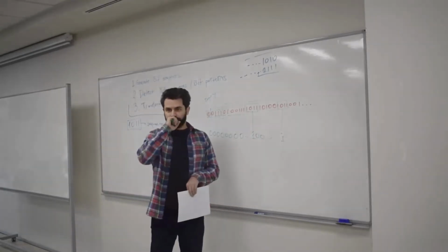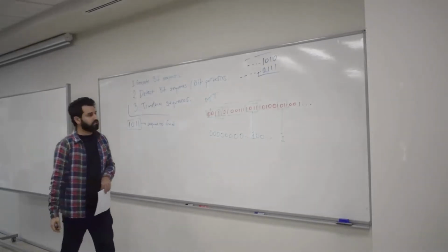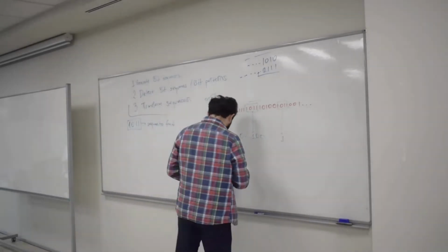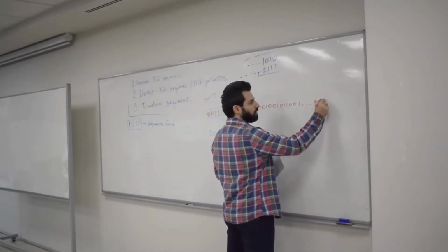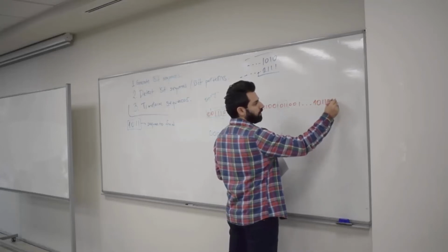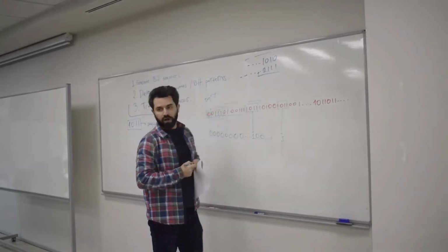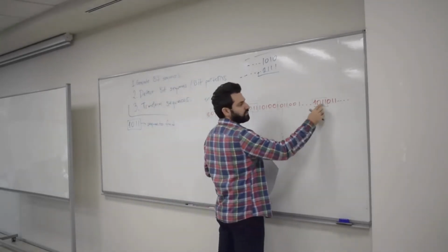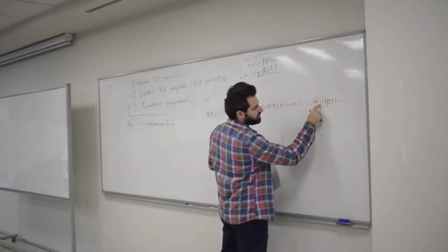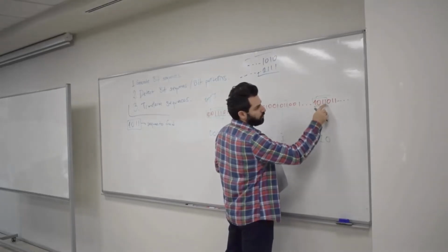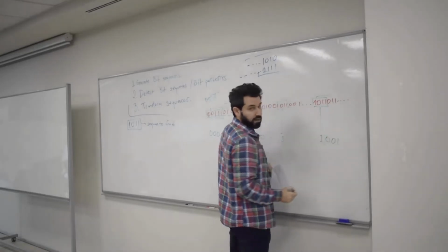One of the things you may want to explore is the following example. It goes on, and you hit, for example, 1, 0, 1, 1, and then 0, 1, 1. What happens in this case? Well, you have this window, 1, 0, 1, 1, and that's a valid sequence. If you move on to the next one, you get 0, 1, 1, 0, which is a 0, and then 1, 1, 0, 1, which is another 0, but then you have 1, 0, 1, 1. That's going to produce another 1.